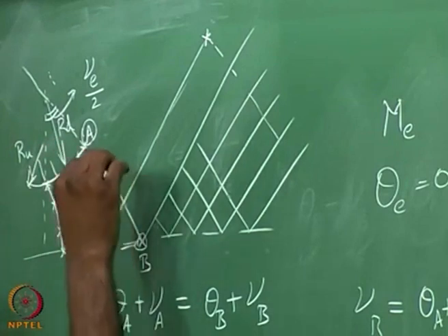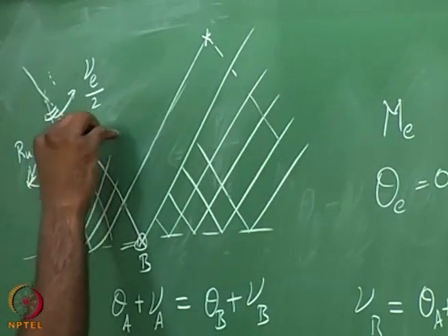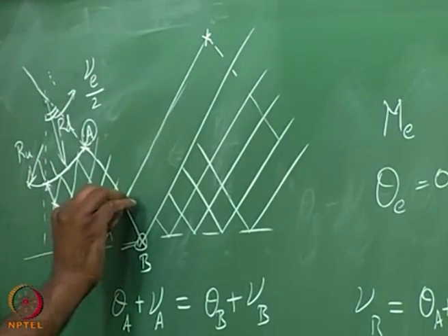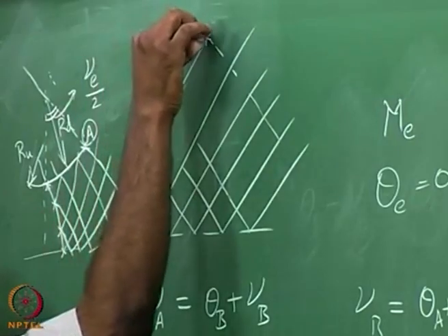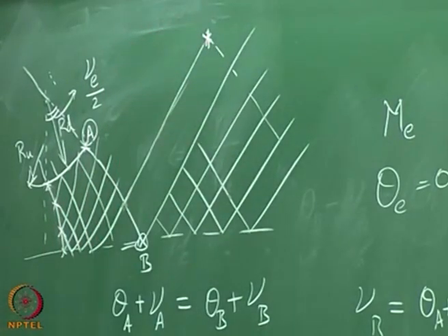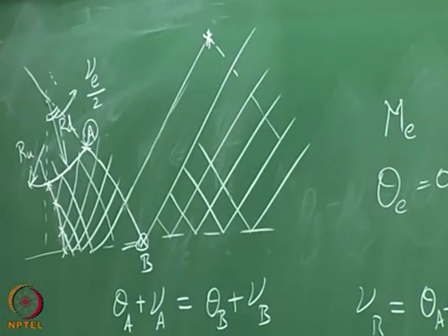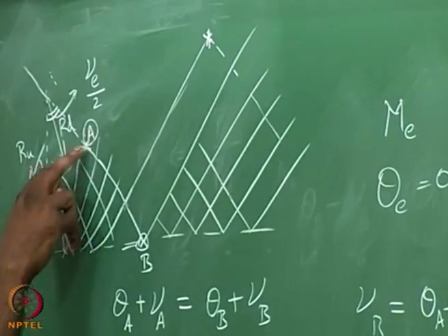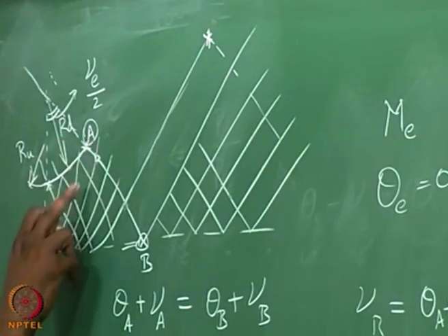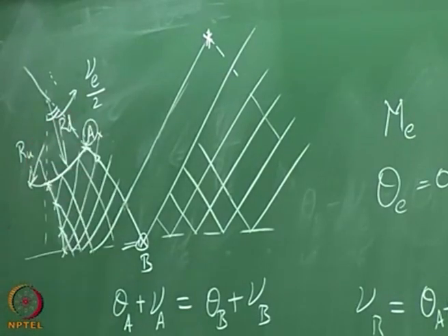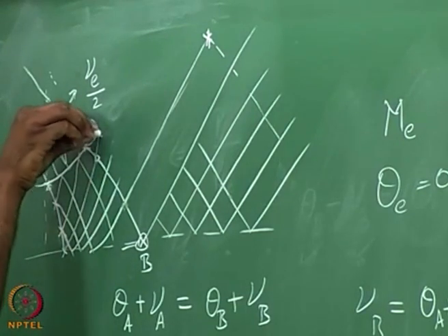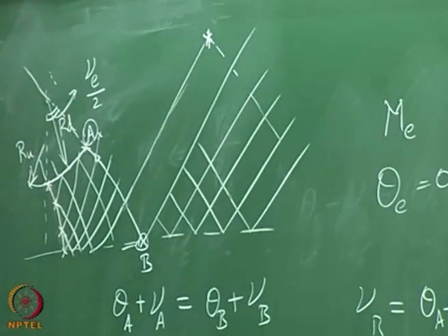So, because of that, what I will do is, the last characteristic I get from here, I will just put the same theta value and nu value at this point on that wall point. That is the key idea of method of characteristics, to create a wall point. To start solving it the logical way, I will start from this characteristic, first one that is going outside of A. I will pick this point, I will take that wall point, put this same theta and nu here on that point. I still have to find the xy.